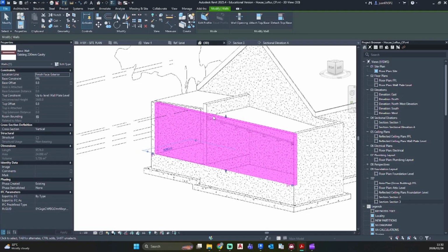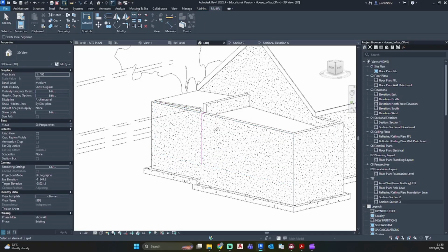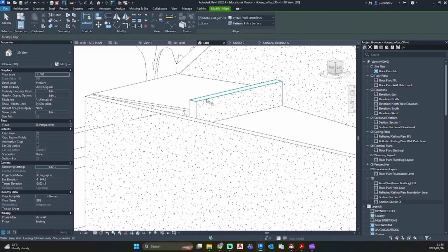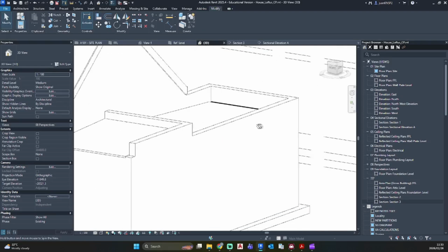So it seems like this wall is also split, that this corner is on the same height and this front part is on this decking height. So I'm going to go SL again. SL, cut it, go AL, and I'm going to lock that in place.